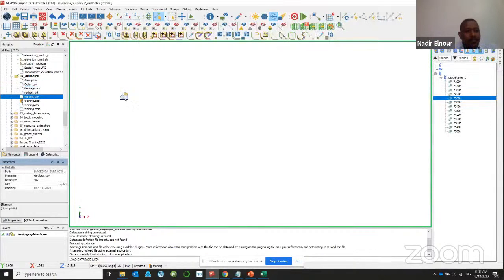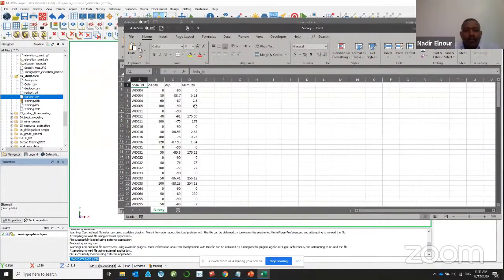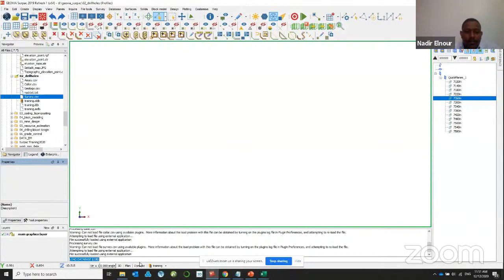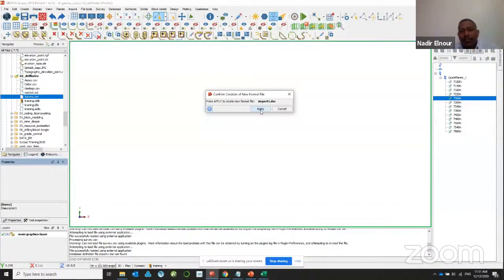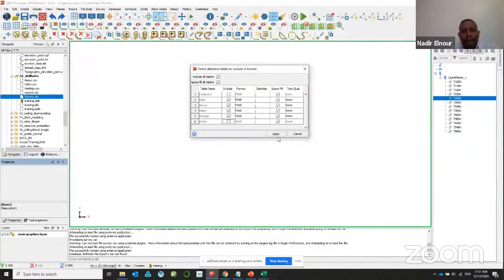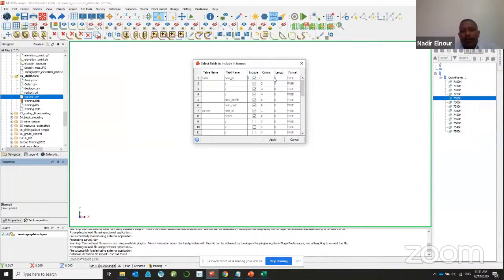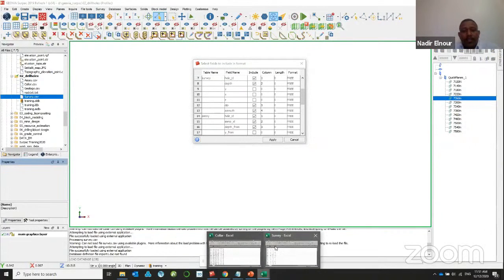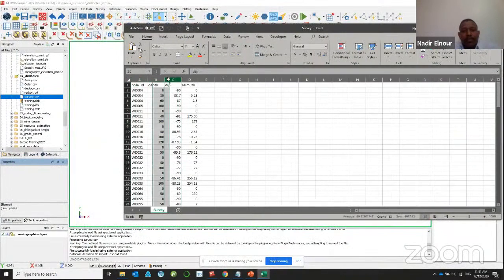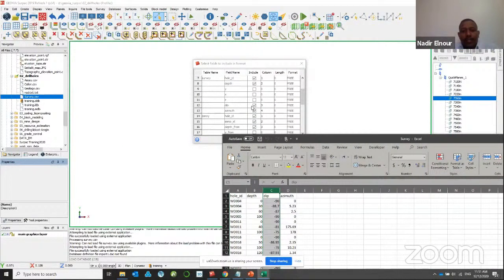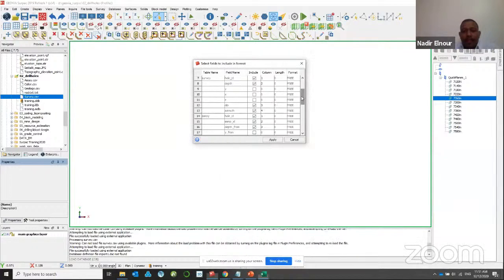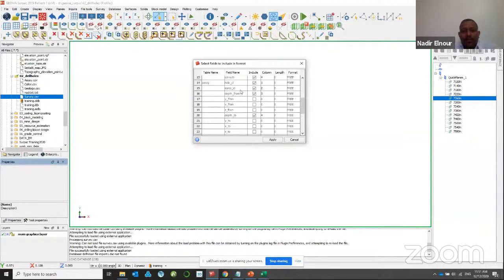And in survey, we have dip and azimuth. Then you just come back and do these very quick imports. We have the hole ID as said there, and also here the dips. We have the dip as number 3. You can see it here. The dip is column number 3: 1, 2, 3. So the dip here I'll put as number 3. Azimuth is number 4. Then when you go down to the assay, you don't have sample ID, so depth from will be number 2. Depth to is number 3.